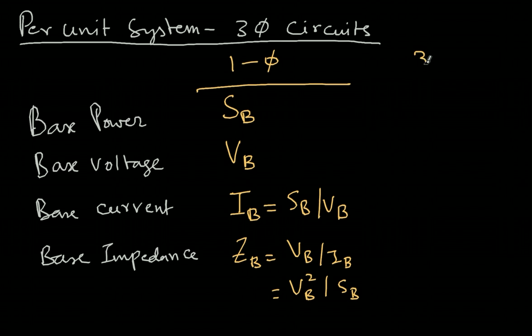Now what happens if I move over to a three phase system? Let's use a different color. The notation is S base three phase. What is the relation between S base here and S base three phase here? Strictly speaking, there is no relation, because the one phase problem is a different problem and the three phase problem is an independent problem. You don't have to have these two related. However, if for the same problem I want to consider both, then these two will have a relation. One phase power, in a balanced system, will be one third of the three phase power.